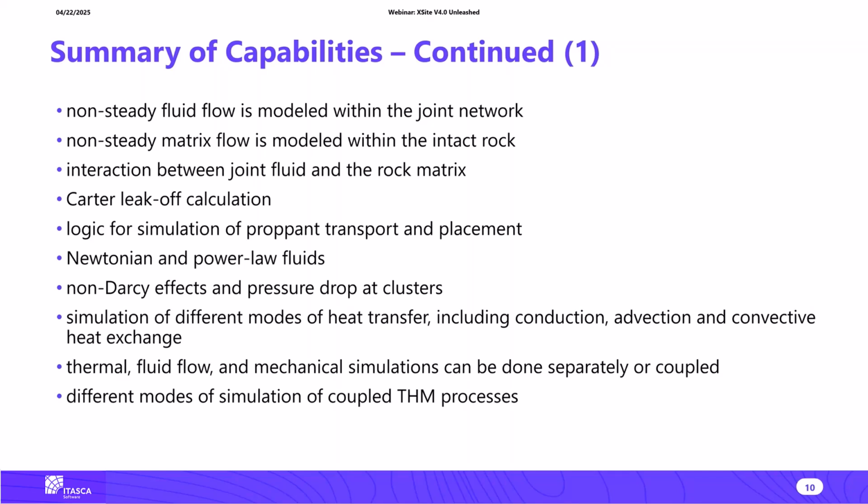Each of these simulation modes, flow, mechanical, or heat transfer, can be done either coupled or separately. So you can just run the model to mechanical equilibrium, or you can run the model for steady flow. The code also includes different coupling modes for simulation, where we can do tightly coupled processes, where all processes are done basically every step, and coupling is two-way.